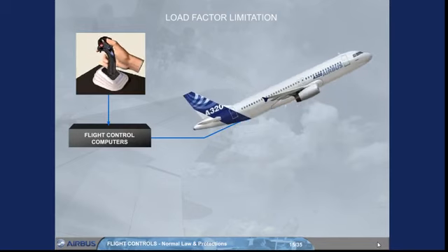Full side stick movement is always available. The load factor is automatically limited to plus 2.5 G to minus 1 G in clean configuration, plus 2 G to 0 G in other configurations.